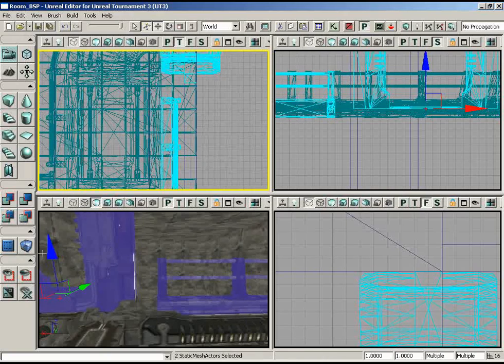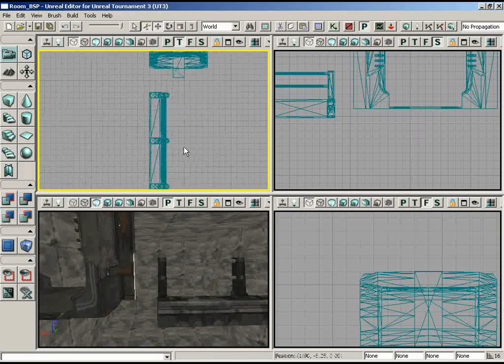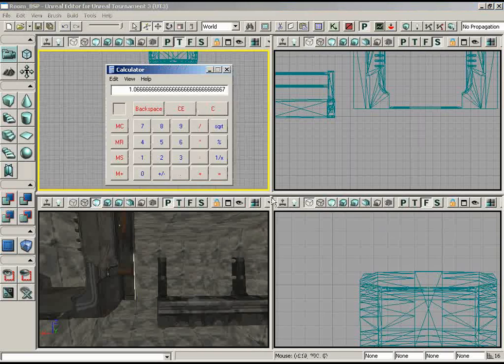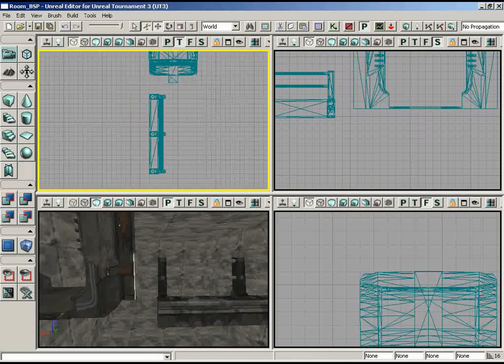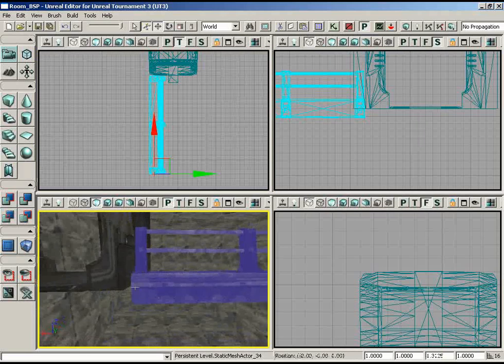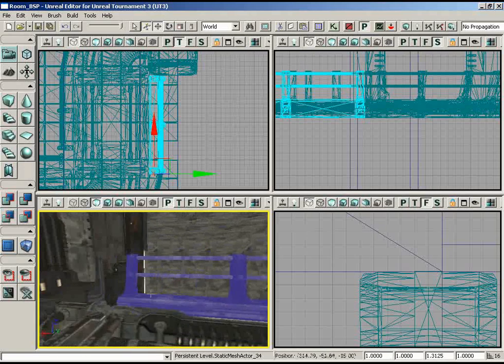We know we're going to that guy, so in order to clean up the view, let me show only these two meshes. Let me figure out what desired length I'm looking for here. So I'll measure out from the edge up until here, and that's 336 units. So 336 divided by 256 gives us 1.3125. We'll copy that, grab our guardrail, and drop that in for draw scale in Y. And that has us aligned nicely there. So we can bring all of our meshes back. Very nice. And that has everything lining up there.